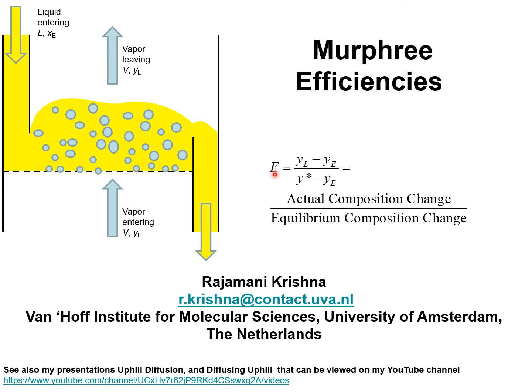For a ternary mixture, there is no fundamental requirement that the component Murphree efficiencies of each of the components in an n-component mixture be equal to one another. And indeed, the objective of this presentation is to explore the consequences of unequal component Murphree efficiencies on the performance and operation of a distillation column.